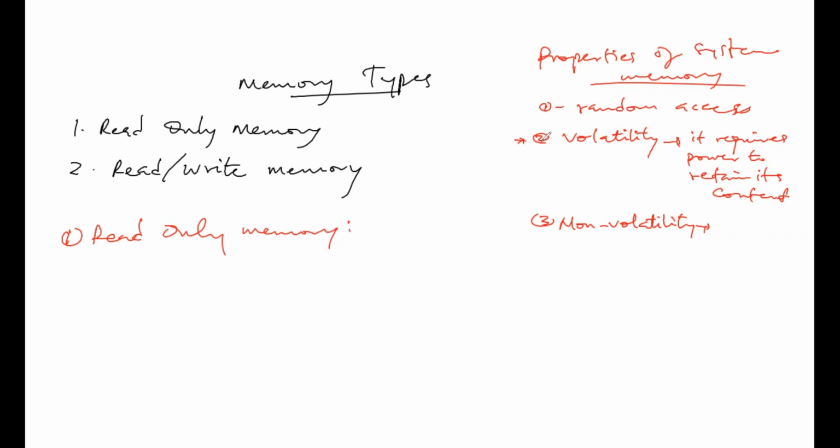And now, some of the read-only memory types we have are the programmable read-only memory. So let's say this is ROM, all right? So we have the programmable read-only memory. And they are useful when the content of the ROM is not yet fixed. That is when the program is still in the developmental stage.